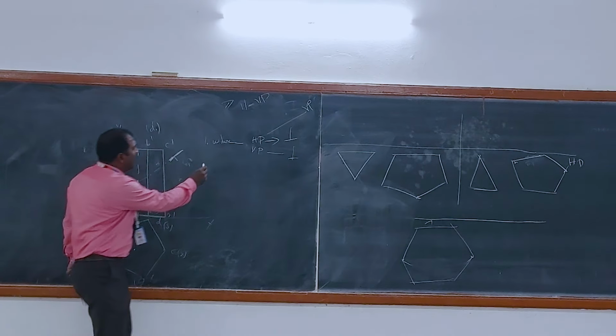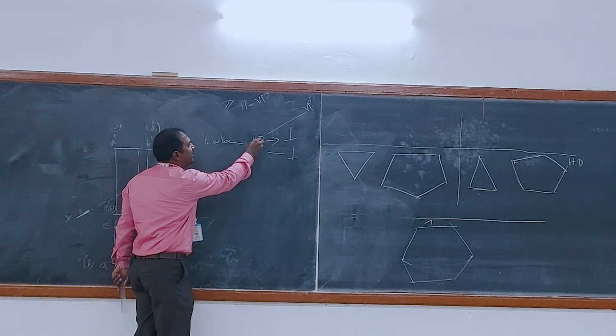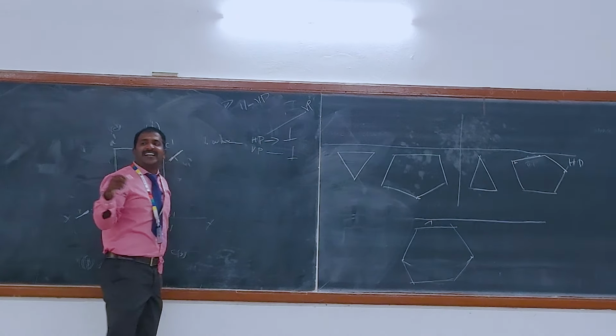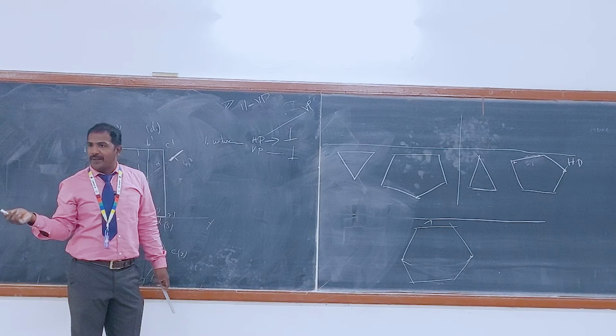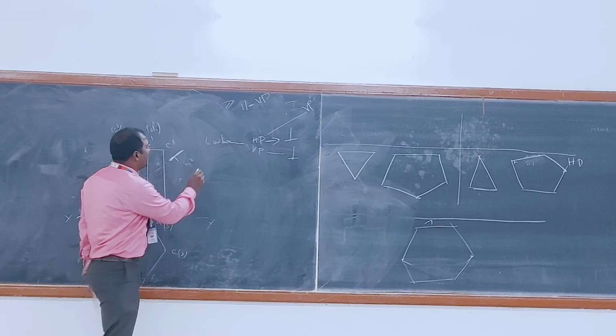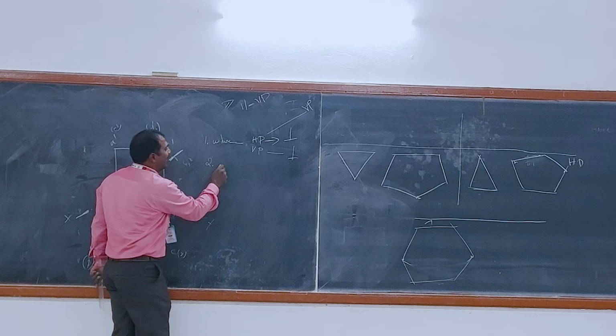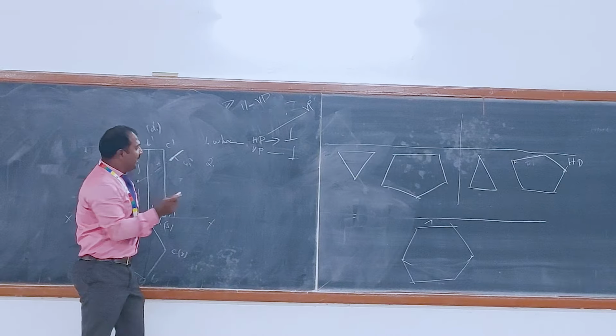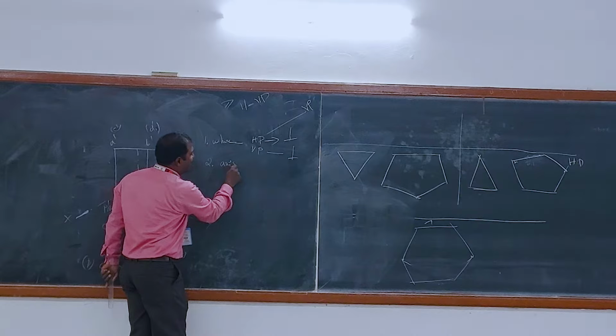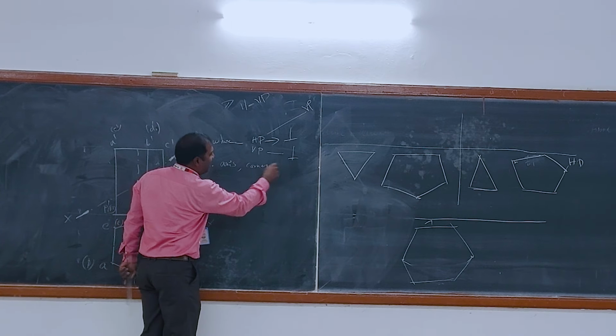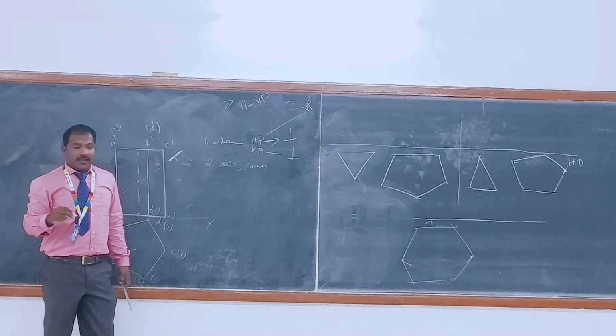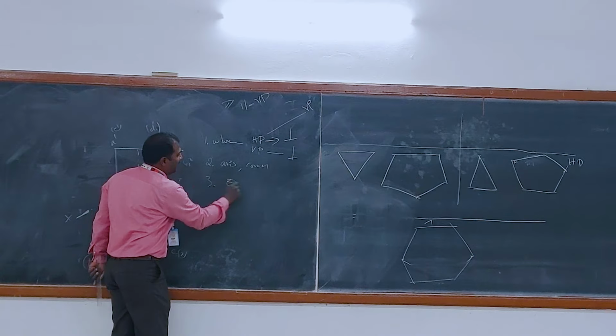These are the conditions. The cutting plane can be drawn on HP or on VP, where it is perpendicular to that particular plane. Second, where it meets: it may be the axis, a corner, or anywhere. And third, how much inclination.